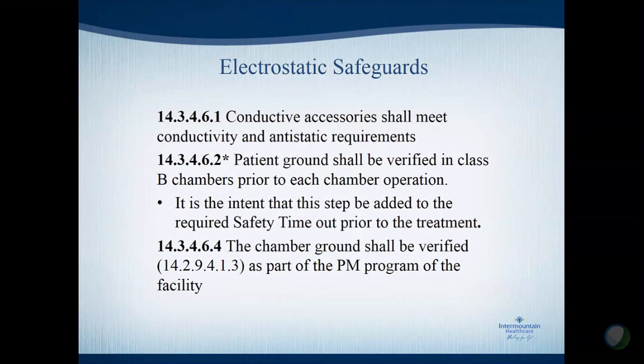So we state that conductive accessories shall meet conductivity and anti-static requirements. We've added some language that the patient ground shall be verified in Class B chambers prior to each operation. That's not an annex note, that's code now. So before you start a monoplace treatment, you check the patient ground. And it's our intent that this step be added to the safety timeout prior to the treatment.